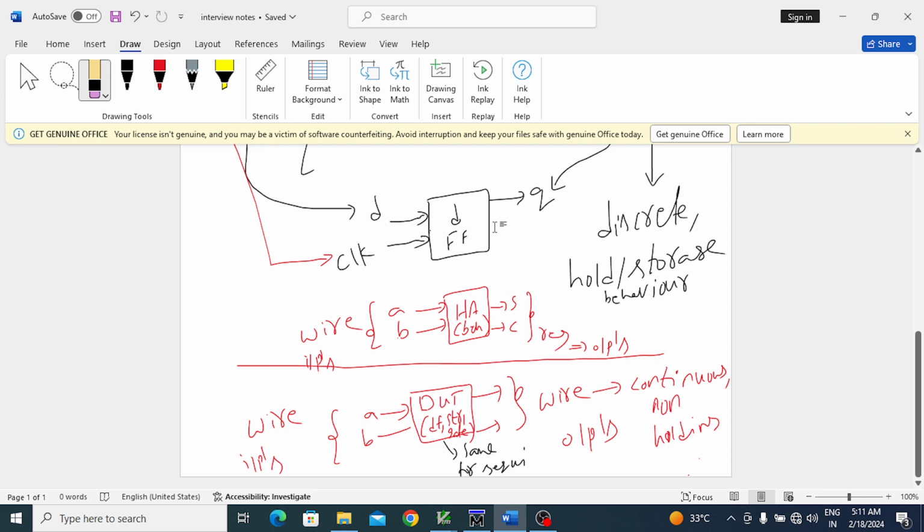This is not about sequential needing storage and combinational not needing storage. Here, what is the intention I told? Until getting the next output I have to store this present output. Like that, in combinational also, until getting the next output, it has to store the present output. For that only, even for combinational, the output should be reg.